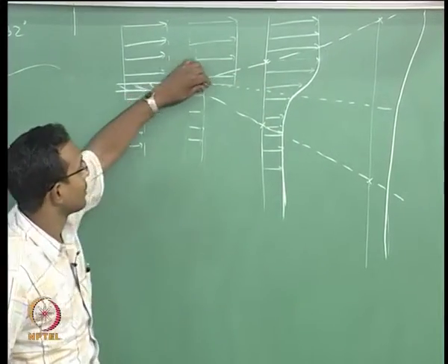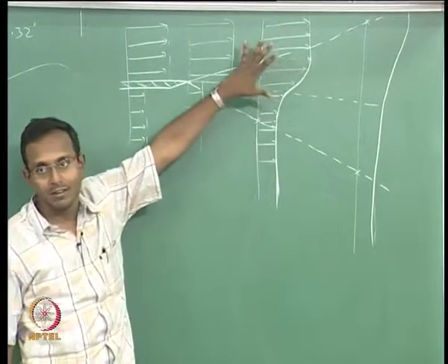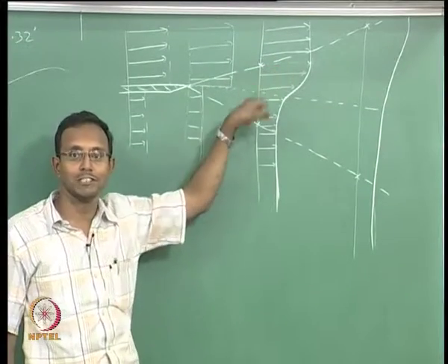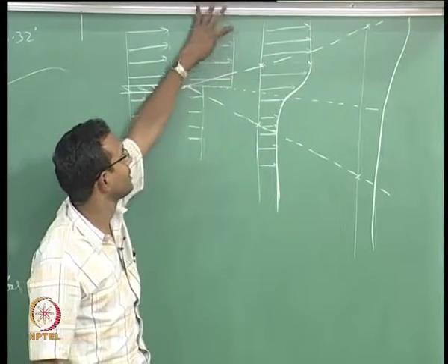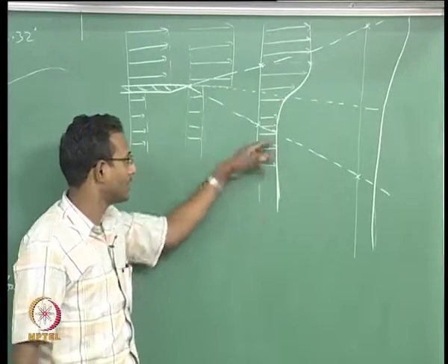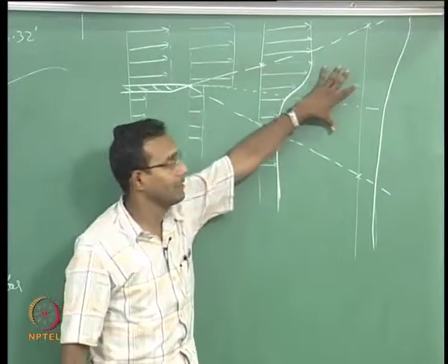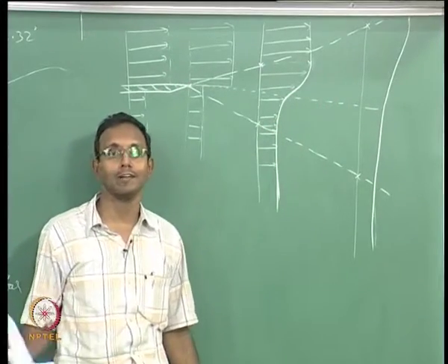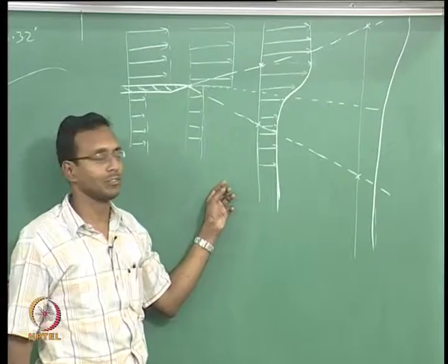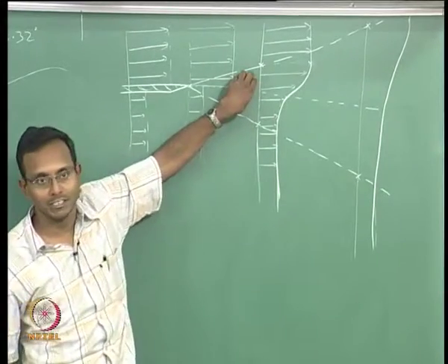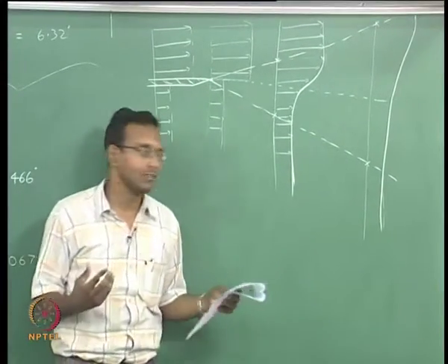This particular region or the band of fluid elements I am considering is the only region where viscous diffusion or vorticity redistribution is happening. Outside this I am going to say the velocity gradients are almost 0, same thing below, almost 0 velocity gradients. So, there is no vorticity. So, this particular region is called the region of shear forces or the shear layer. This layer is in between the 2 regions where there is not much of viscous forces. And if you do more of a fluid mechanics course, you will start seeing that.